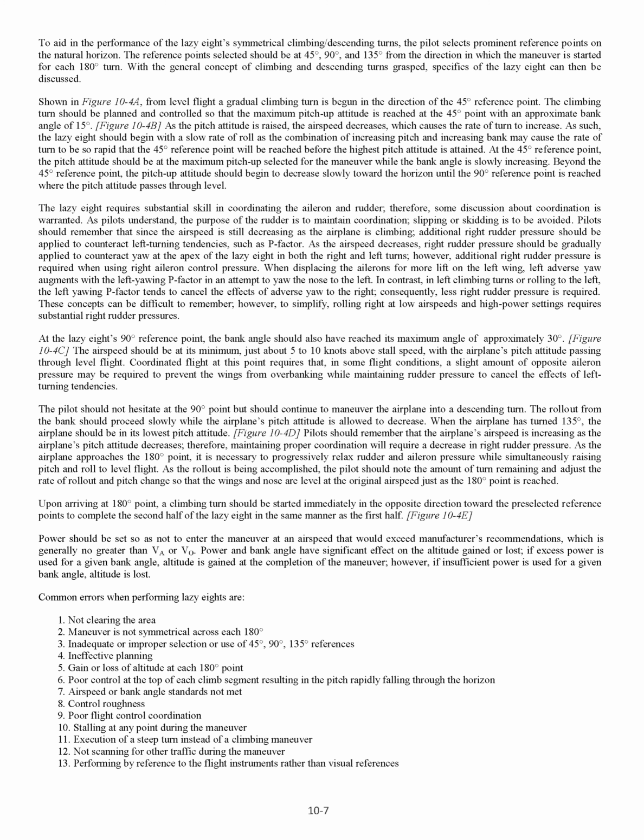The Lazy 8 requires substantial skill in coordinating the aileron and rudder, therefore, some discussion about coordination is warranted. As pilots understand, the purpose of the rudder is to maintain coordination, slipping or skidding is to be avoided.